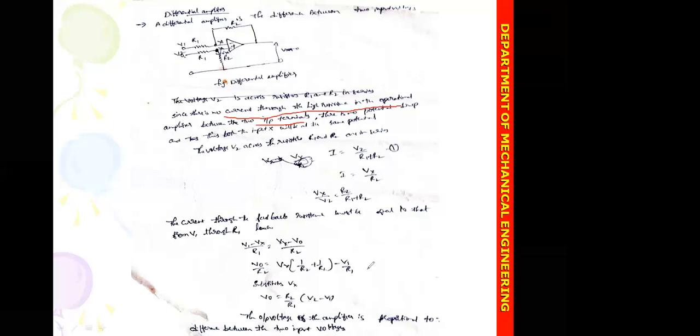So here, you know that V2 is equal to R1 plus R2, so R1 and R2 are in series. That is I is equal to V by R, that means V is equal to IR. That means V2, the two resistors being in series, in the place of R it becomes R1 plus R2. So I is equal to V2 by R1 plus R2.